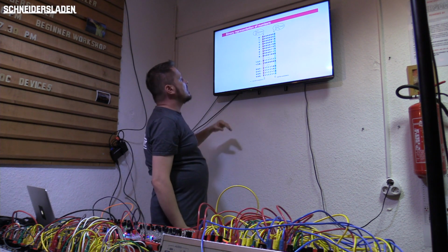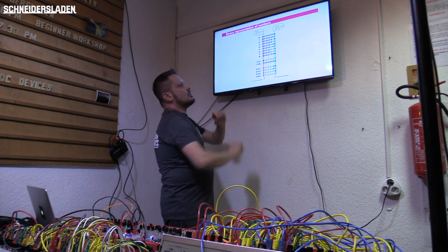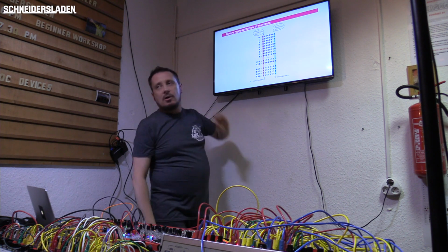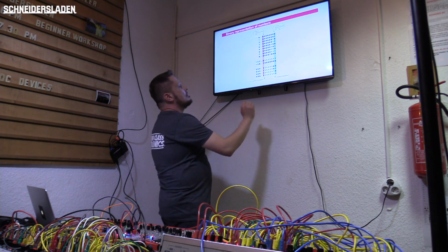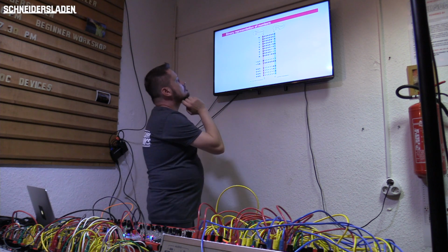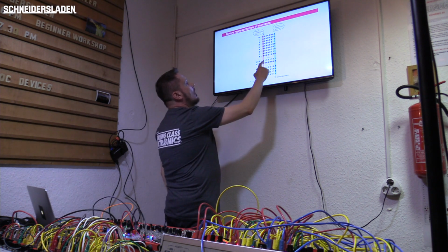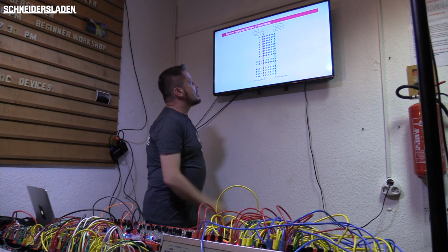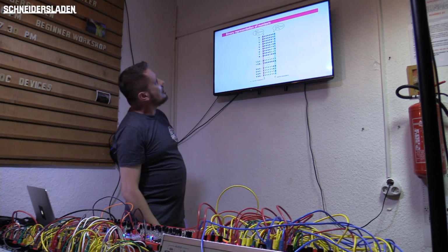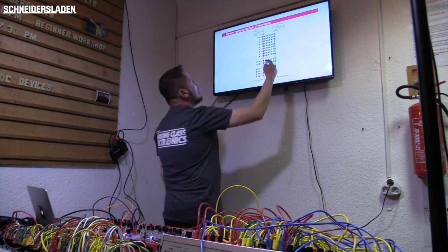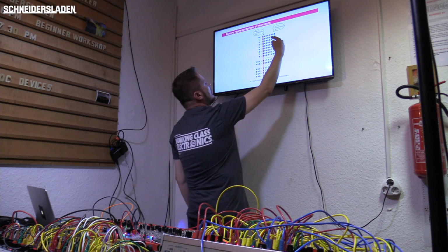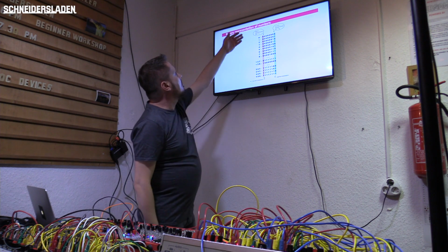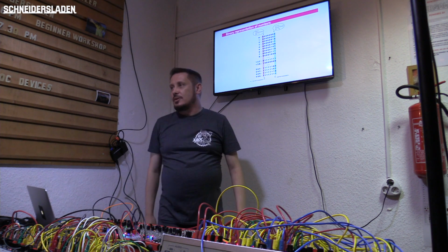You can see that the highest value that you can represent with 8 bits is 255, and in the middle of this range there is a very interesting switch from all ones to just 1 at the highest position and zeros. If you look at them from top to bottom, the least significant bit flips in the most rapid way, and the most significant bit flips slowest.